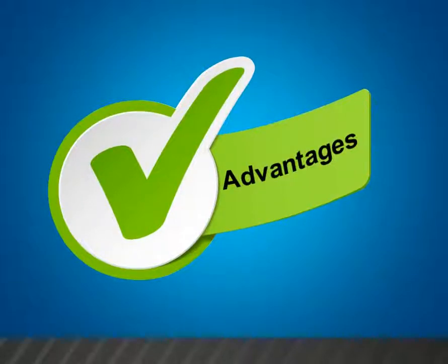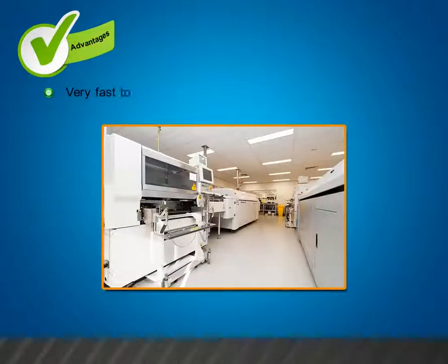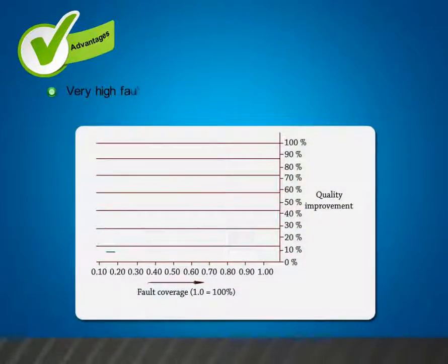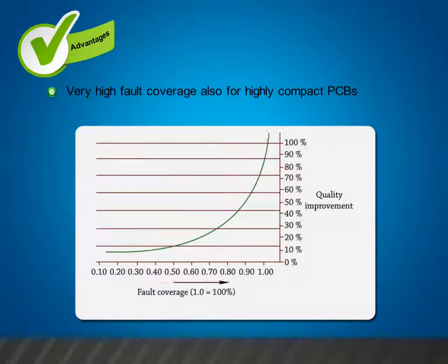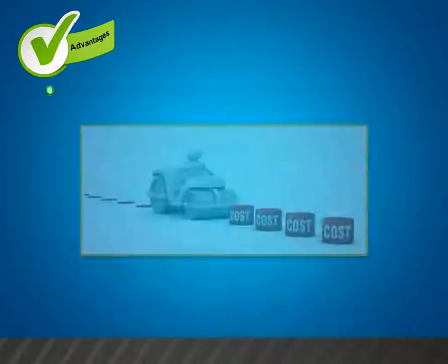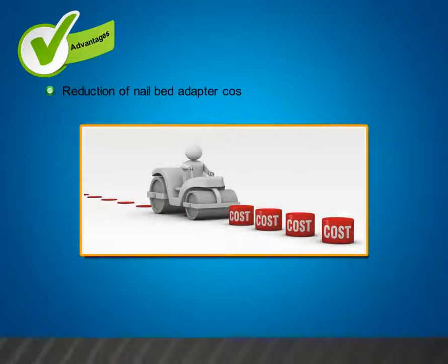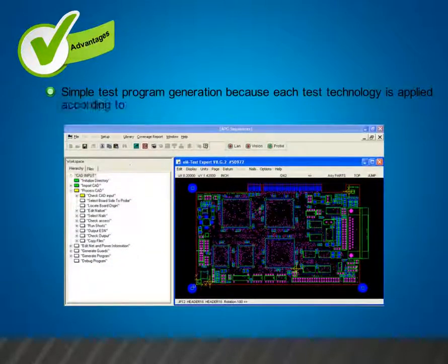Advantages of in-circuit testing: very fast total system, very high fault coverage also for highly compact PCBs, reduction of nail bed adapter costs, and simple test program generation because each test technology is applied according to its core competence.